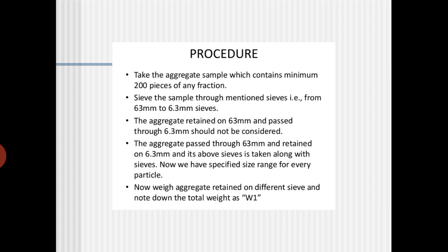So normally, to strengthen the subbase layer of the roads, 80 to 100 mm aggregates will be used, and it is compacted with the roller. Normally a 100 ton roller will be preferred in case of strengthening with 80 to 100 mm aggregates.